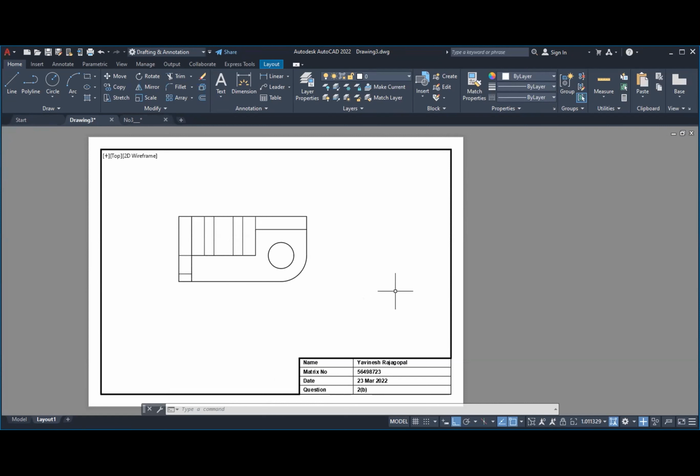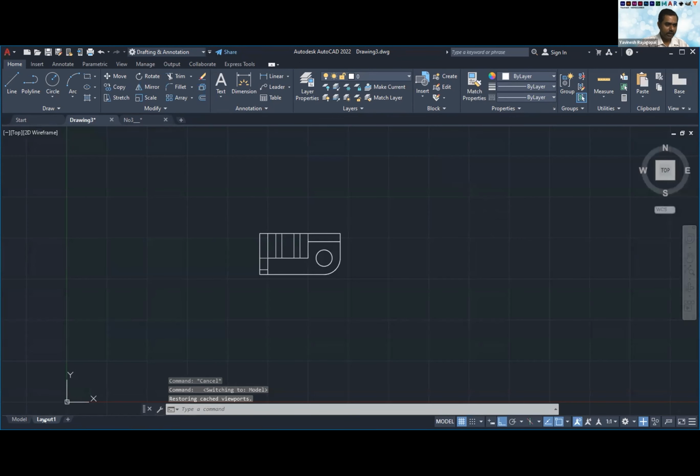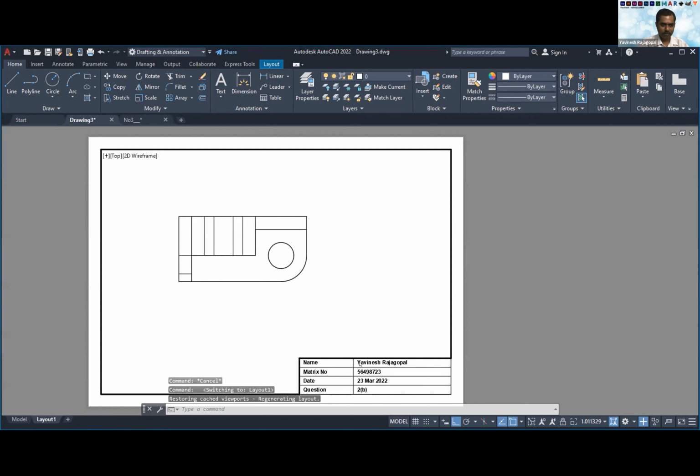Yes, sir. So it means we can create with a new file, right? We open and save. Correct, correct. So once we save the template, a blank drawing, no drawing here, only layout, only the title block. We set up the M view and everything, and then you save as template. Once you save as template, you can create a new drawing, you paste it there.